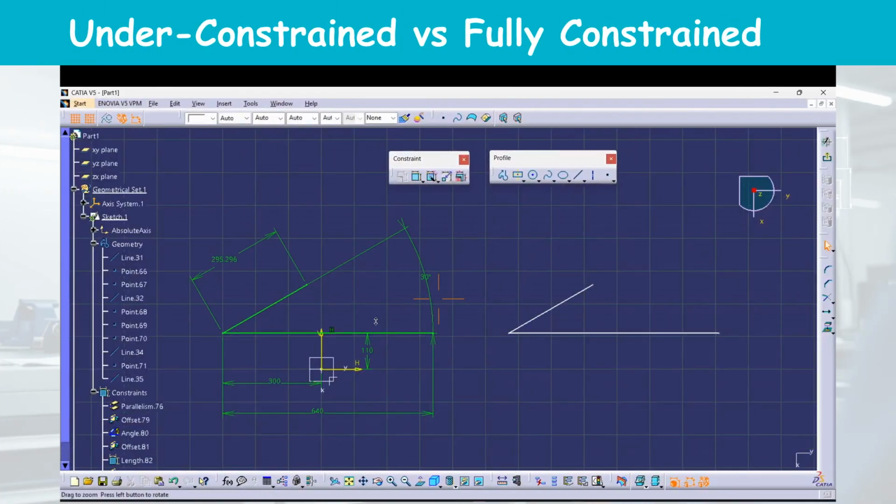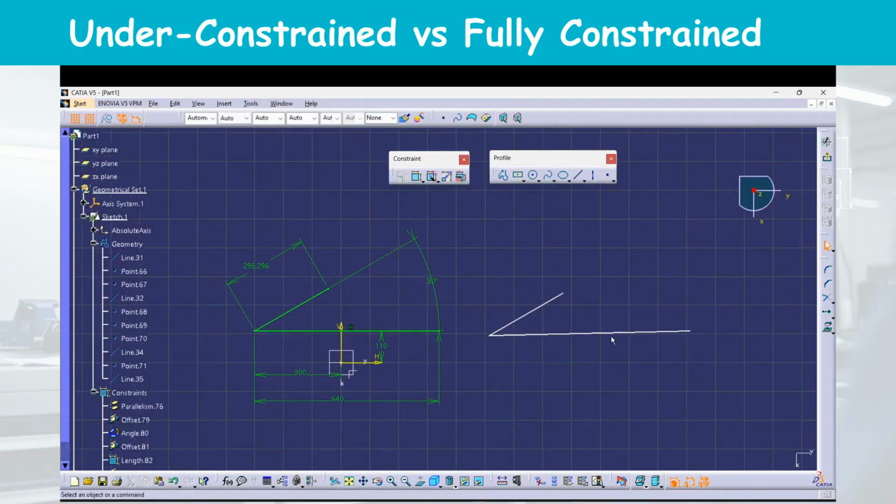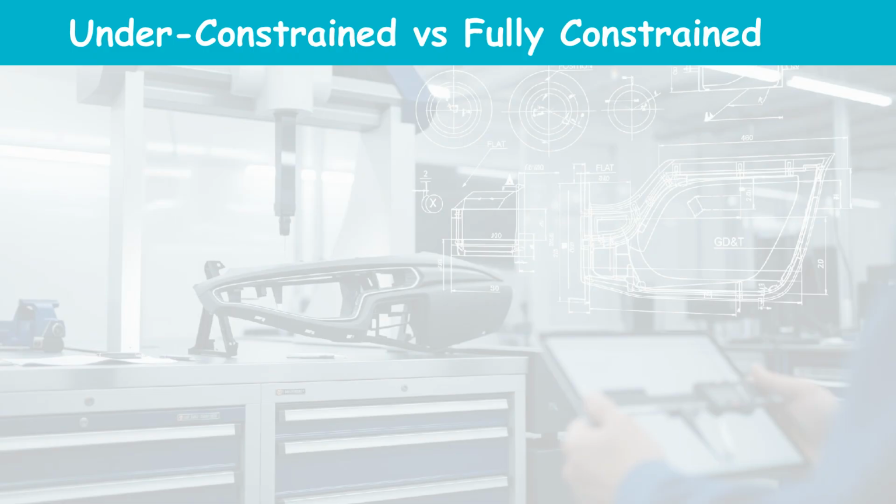Let's compare two sketches. The first sketch is under constrained. Some geometry can still move. The second sketch is fully constrained. Every element is completely defined. A fully constrained sketch is more reliable, easier to modify, and preferred in industry.